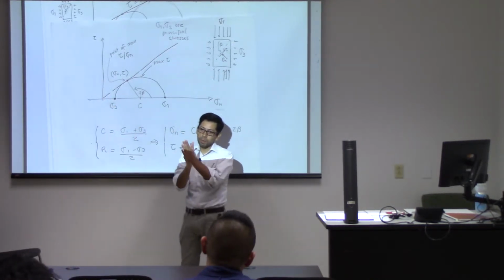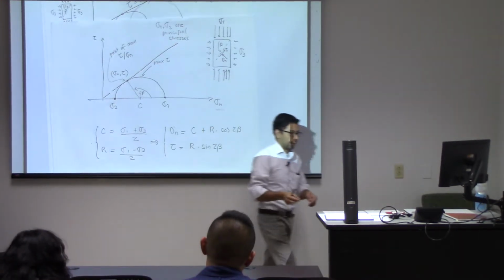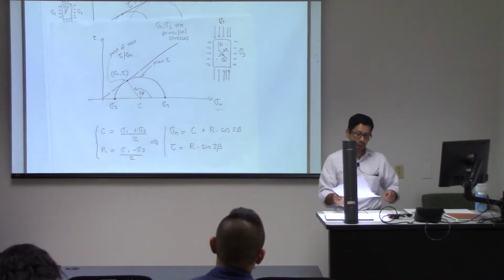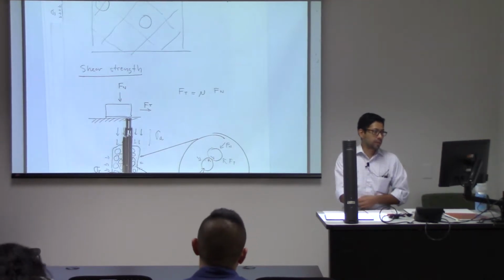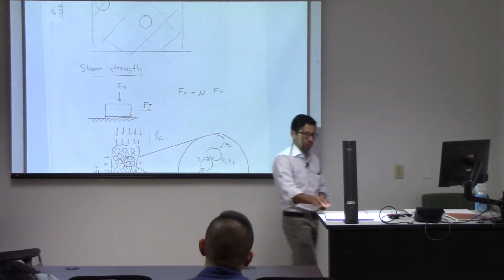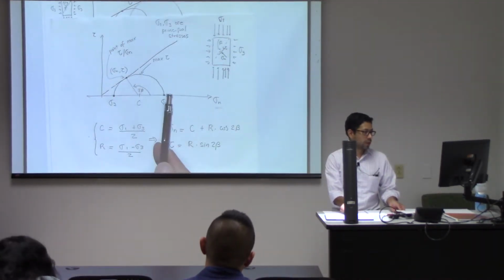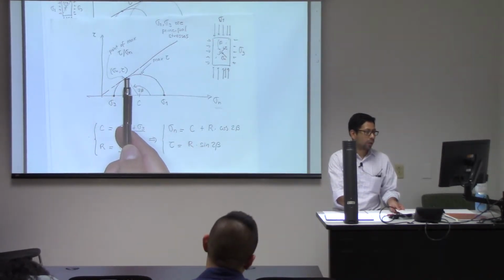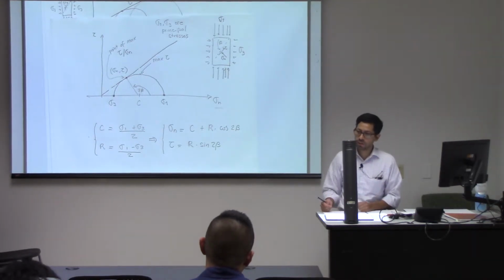So those planes, if I were to move them one to the other, very similar to what we discussed for this case, as long as there is a normal stress and there is no shear stress, this one is not going to move. Okay? And those points are the same. You need enough shear stress and low enough normal stress for those planes to move and to fail in shear.